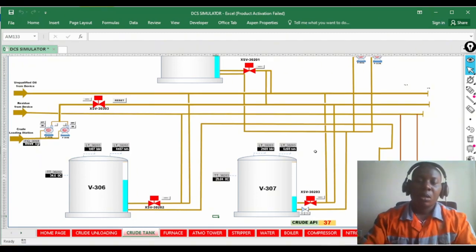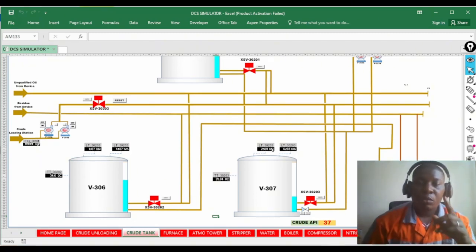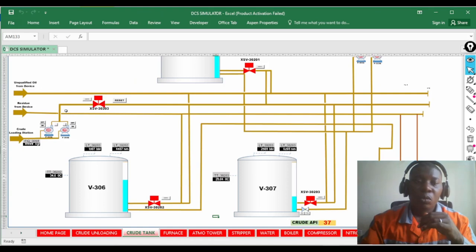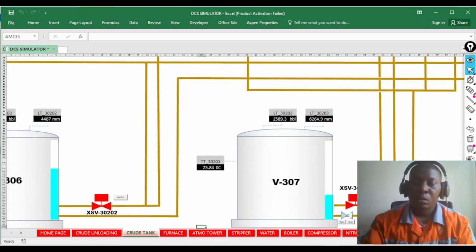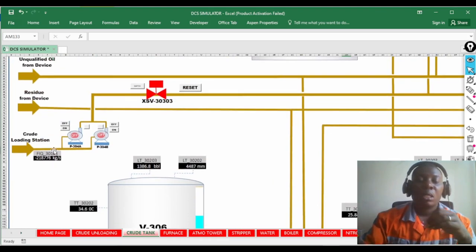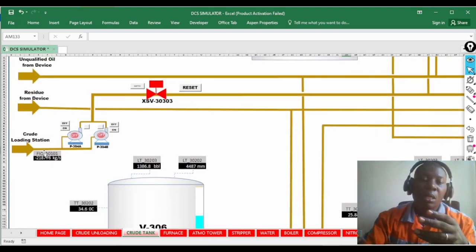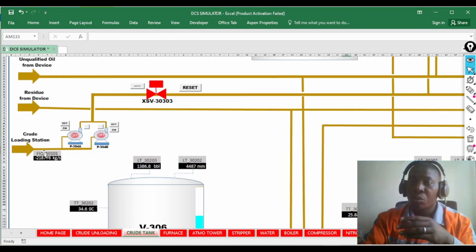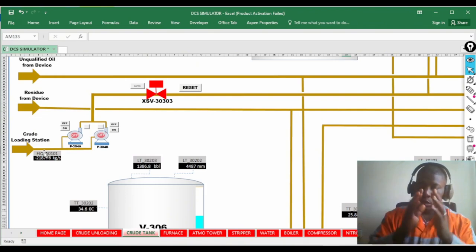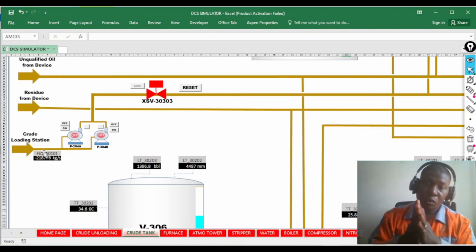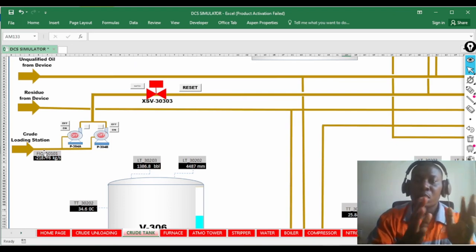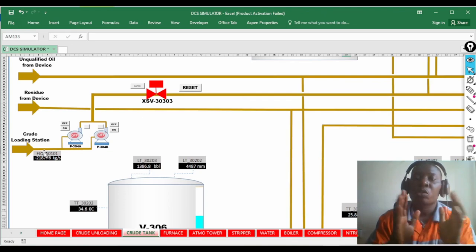All right, so before you go, I have just one question for you, and in this question we'll look at the pump again. Let's go to the pump. So like I mentioned, there is a strainer at the suction of the pump. After the strainer, you can have a drain, then we get to the suction of the pump. Now what if the strainer is blocked? What if it is clogged?